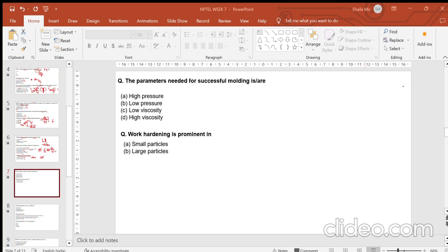There is also one concept where we are saying that de-agglomeration of the material has to be done, right? As I said, we have particles such as red mud that has a natural agglomeration taking place. So whenever you start with red mud powder, for example, you will always go for milling or mixing it. You will send it to a mixer for de-agglomeration because you want the particles to de-agglomerate. You can use a heating method, you can use other methods, but one of the methods is also that you can use a milling process or you can use mixers for that.